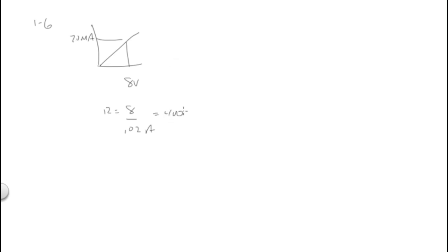400, right? So that's 400 ohms. Now we can use that. It says find the current. I equals what when we have 15 volts. So now we can go back and we say V equals IR. V is 15, I times 400. Okay, so we plug this value in down here, and away we go. I is equal to 15 over 400.